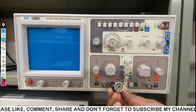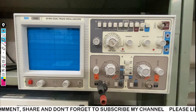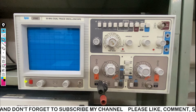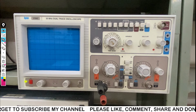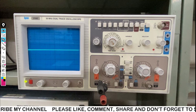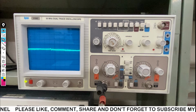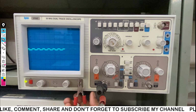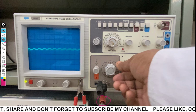So look at here. This is a probe, the test probe we have in our lab. I am inserting it in channel Y, and turning the CRO on by pressing the on button. Look at here, you can see something on the CRO. So there is a line. I'm going to test the probe first. Testing the probe is very simple. Just connect the positive part of this probe to this test point.